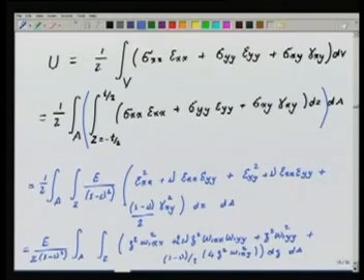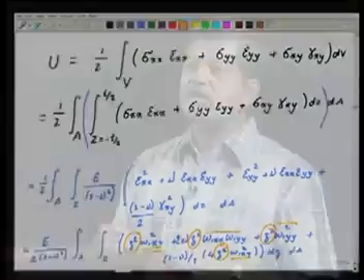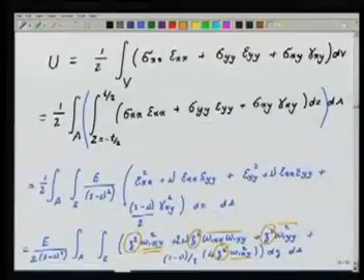So you see that through all these things we have this z squared sitting in each one of these expressions. The integral of z squared, and the rest of them are all functions of only x and y. The w comma xx, w comma yy, w comma xy are all functions of x and y, so they are functions in terms of the area only. So we can explicitly integrate out the part corresponding to the z.